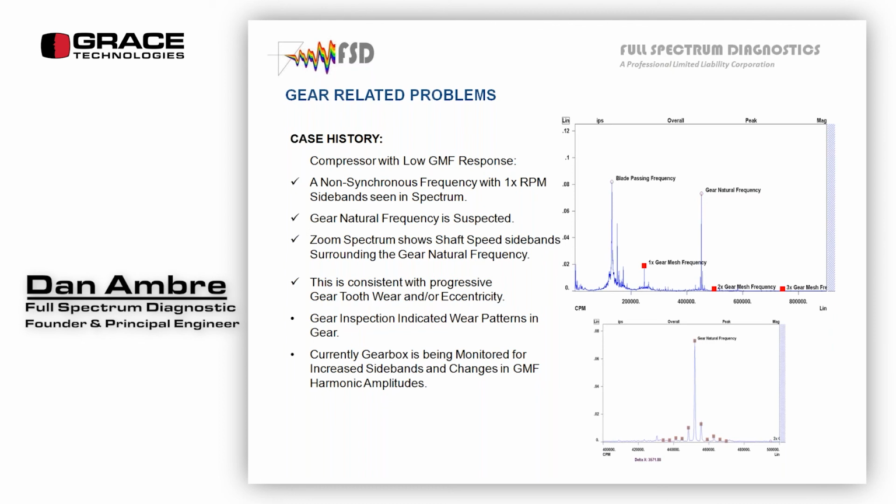One of them failed once. I don't know what it was. It wasn't due to vibration. It was something else. They took it apart, and they had the gear out sitting on a pallet. I went and counted the teeth, and I'm like, oh my gosh, this is not the gear mesh frequency. It turns out that this was the gear mesh frequency down here. So I had a nice pattern, and what I was seeing wasn't a gear problem per se. It was something ringing the gear.